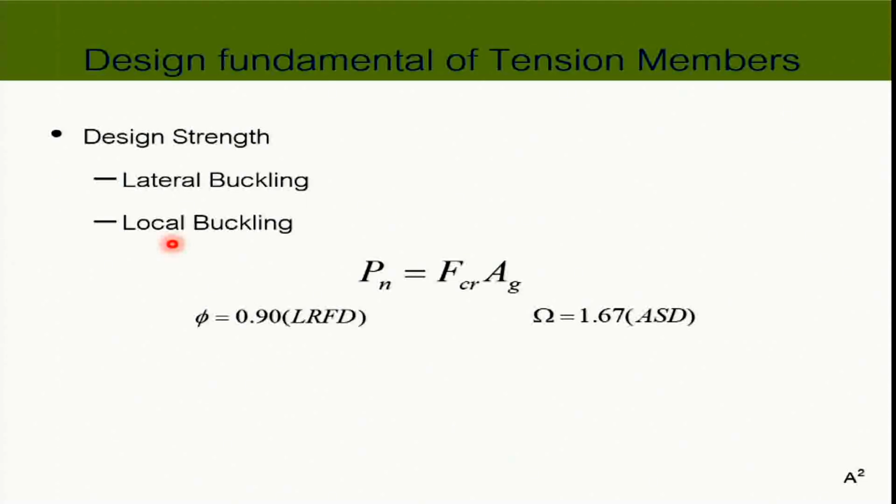I don't want to touch the specific words, because you may think, what is this? I don't get it. So it's gonna fail, and the failure we call buckling. That's all. So if the flange is too slender and it may fail before, or the web is too slender and it may fail before, that will be another issue that will prevent us from reaching F critical.